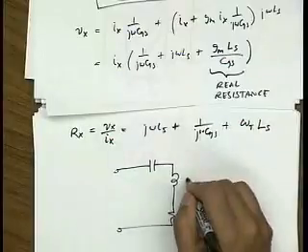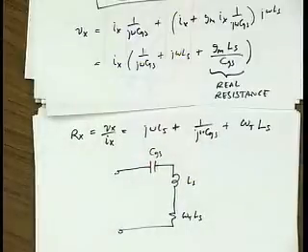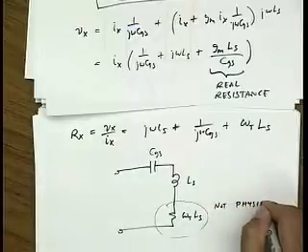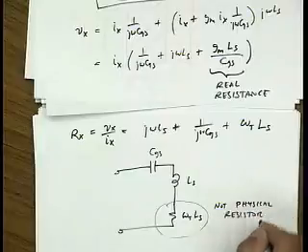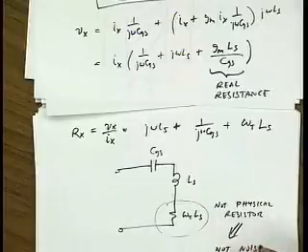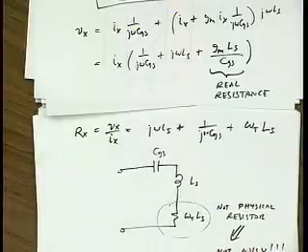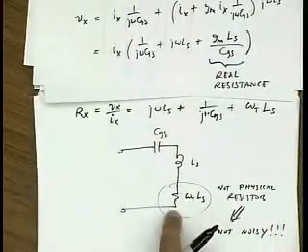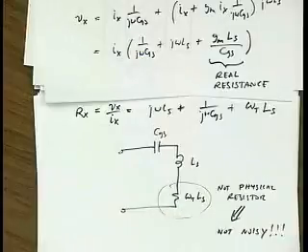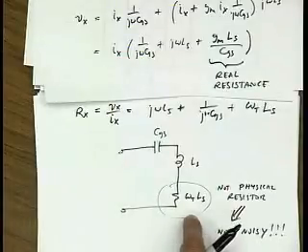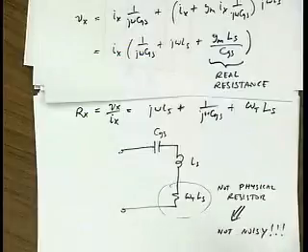And it's important to note that this is not a physical resistor, and so it does not generate noise. The transistor is noisy, and we'll see later on how the transistor introduces noise. But you can't think of this as a physical resistor and say, ah, I just have noise associated with this. Because this is equal to the source resistance, the noise figure would be at least 3 dB worse, right? If that were the case, this would be useless. We'd just lose all the good noise properties right away. Okay.